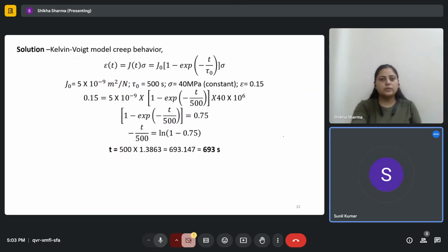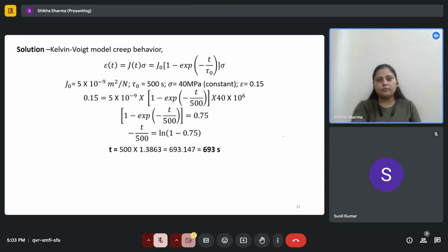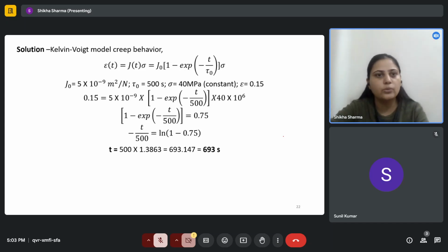693.15. Yes, your answer is correct. We are solving this by applying the Kelvin-Voigt model for creep behavior. So the strain at any time is equal to the creep compliance times the stress.